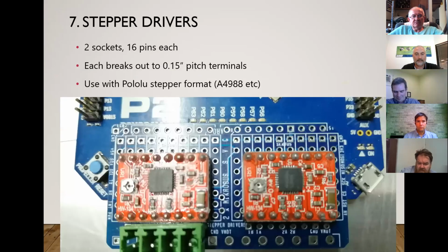And then the final mode is for just running stepper motor drivers, like found in 3D printers and little mini mills and just about everywhere nowadays. Because the data pins are running across the top of the header here, all we've done is add the second set down here, which break out to screw terminals or plug-in terminals, so that it makes it easy to connect up stepper motors to the boards.